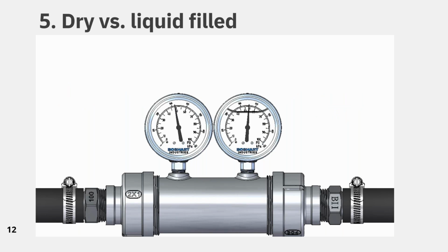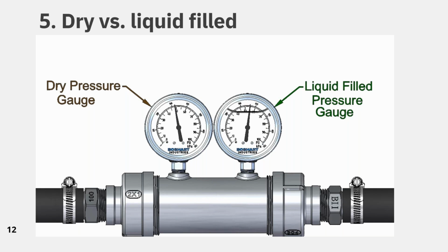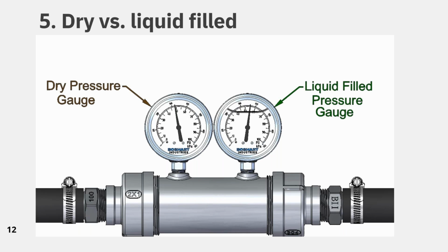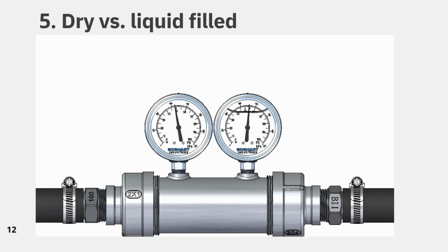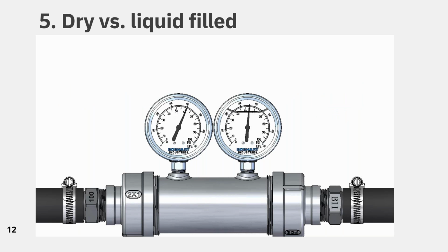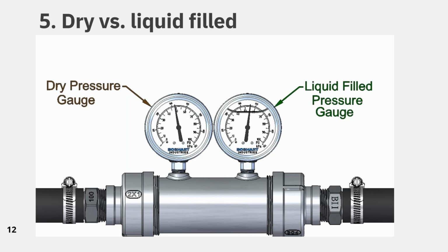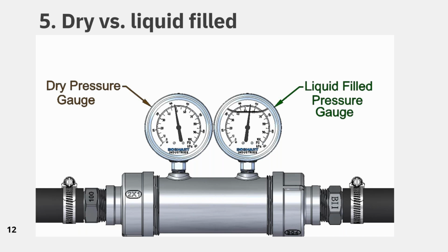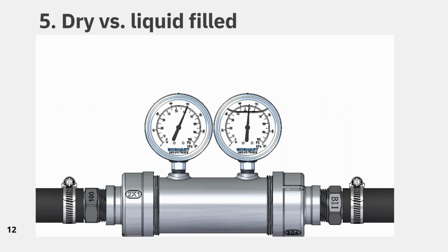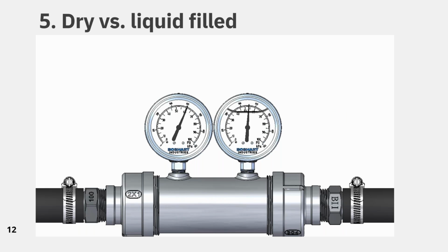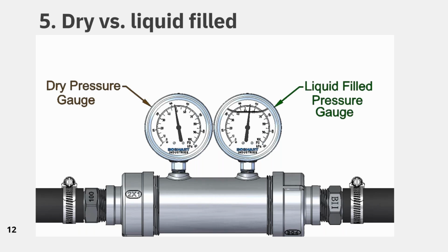When lowered to plus 17 degrees Celsius, glycerin starts to become viscous. As the temperature further decreases, the glycerin becomes even more viscous and causes the pointer to move more slowly to the correct position. At -5 degrees Celsius, these gauges are no longer able to operate. For operating temperatures less than -5 degrees Celsius, glycerin should be mixed with water. A ratio of 2 parts glycerin and 1 part water lowers the freezing point from -5 degrees Celsius to -46 degrees Celsius. This 2/3 glycerin mix can now be used in colder temperatures.